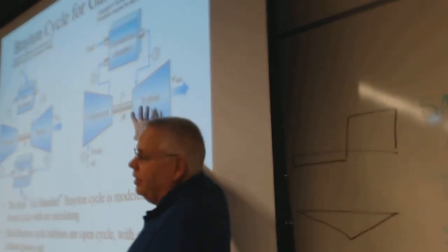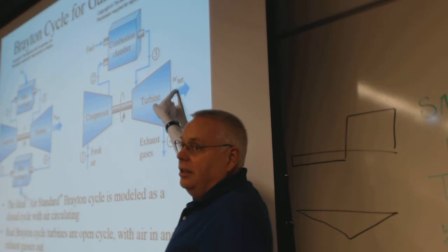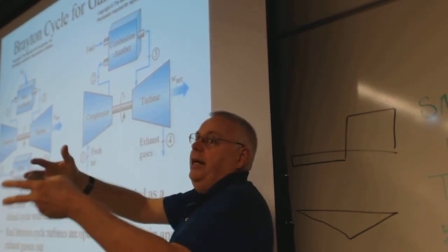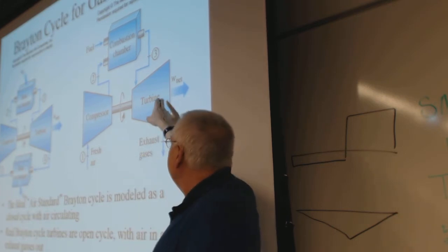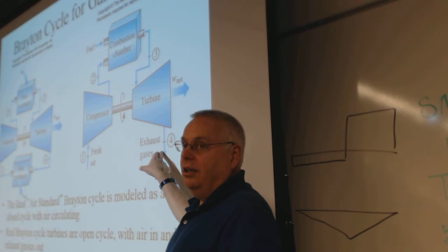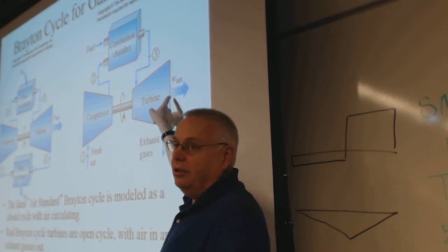But both of those would have to do with this diagram. It's just, are you emphasizing shaft work coming out here and using it to blow more past the engine, or are you leaving more energy in the exhaust gases to go faster and not use the work to increase the mass flow?